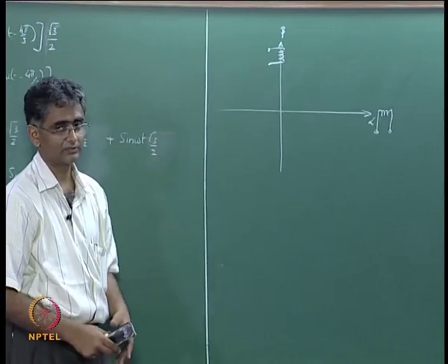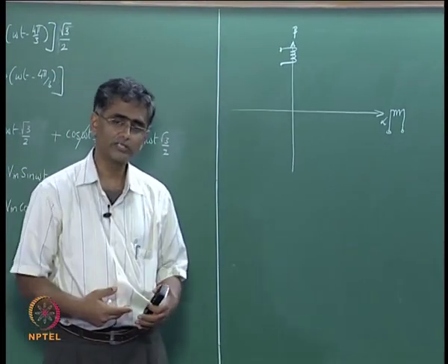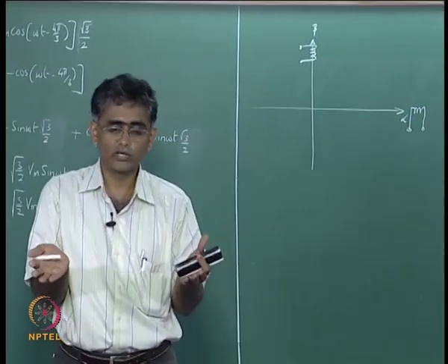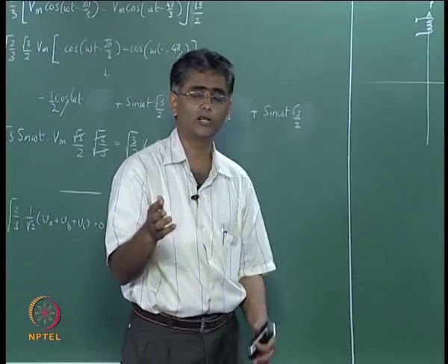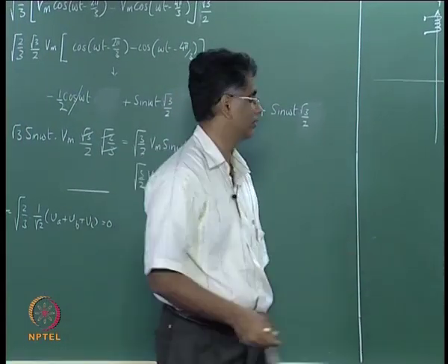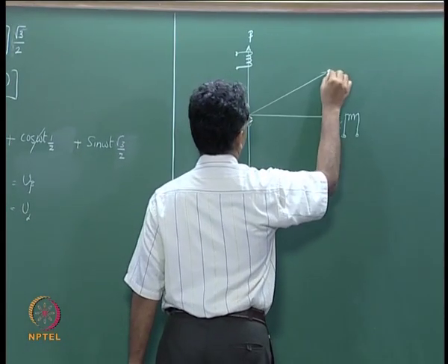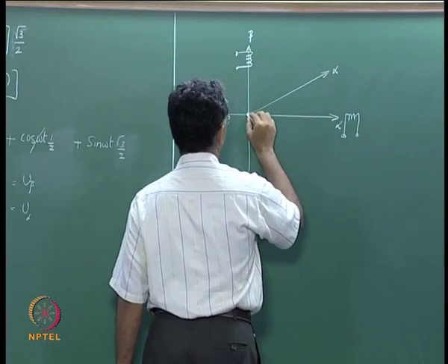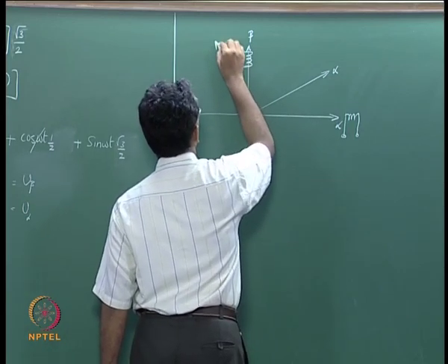along the beta axis, and similarly the ABC of the rotor have also been transformed into the alpha beta reference frame, but however the alpha beta of the rotor are rotating along with the rotor, and therefore you have an alpha axis of the rotor and a beta axis for the rotor.